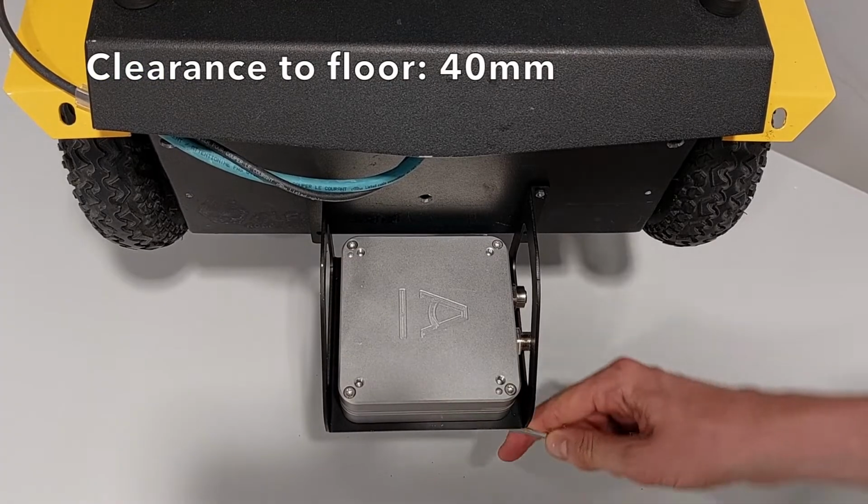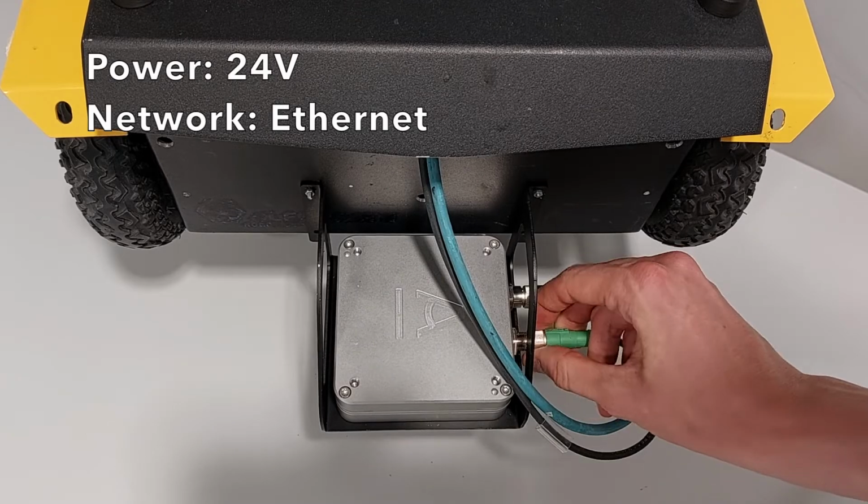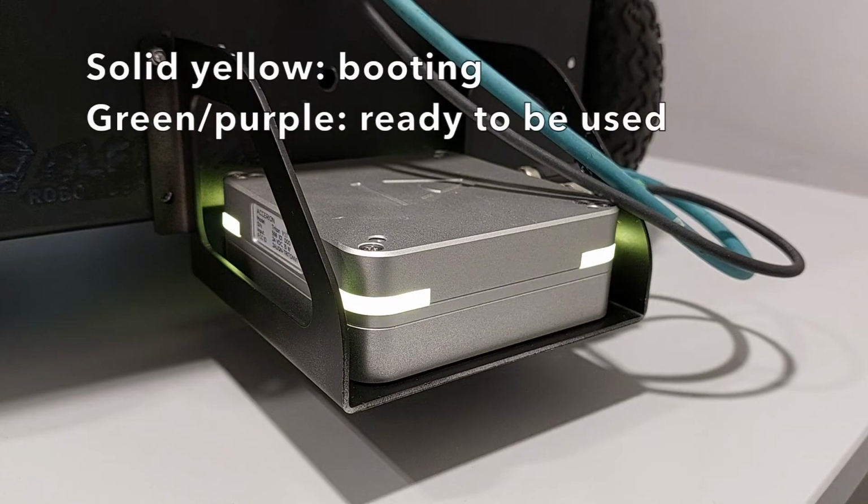It is best mounted as closely as possible to where you need your accuracy, and it's mounted 40 mm off the floor. Triton needs 24 volts and connects to your robot via Ethernet. While Triton is booting, the LEDs will be yellow, and after it's done booting, they will blink green and purple. Now let's move on to the software integration.